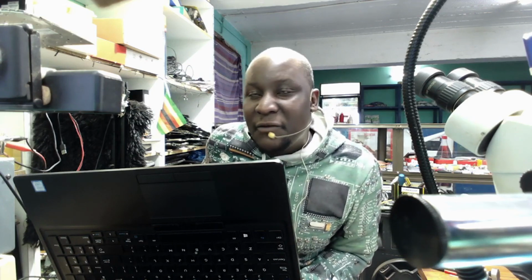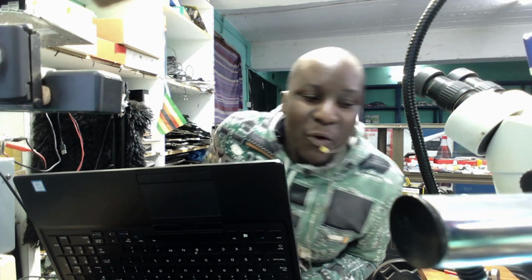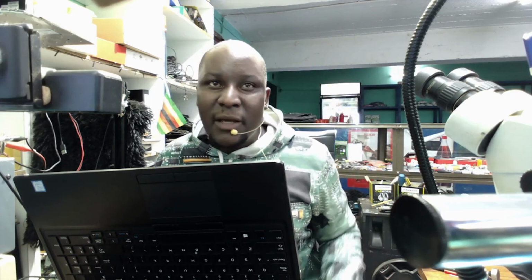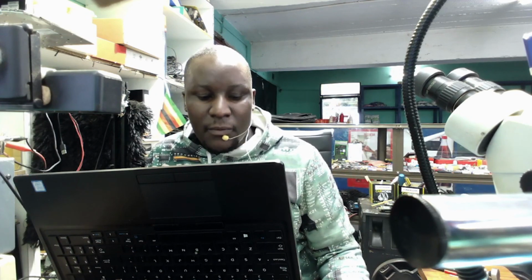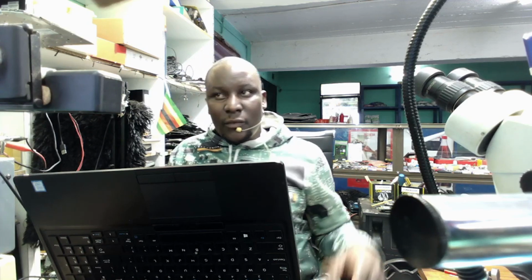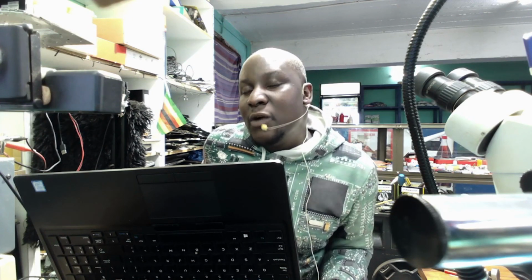I'm happy if I can fix something without schematics. That was a lucky case. When you find the blown up component, you replace it and the motherboard is working. So you see how things work. This is some kind of new model, and the main power rail is generated after the PD controller. It's not working with 19 volts on every switching power supply, but it's working with 13.5.